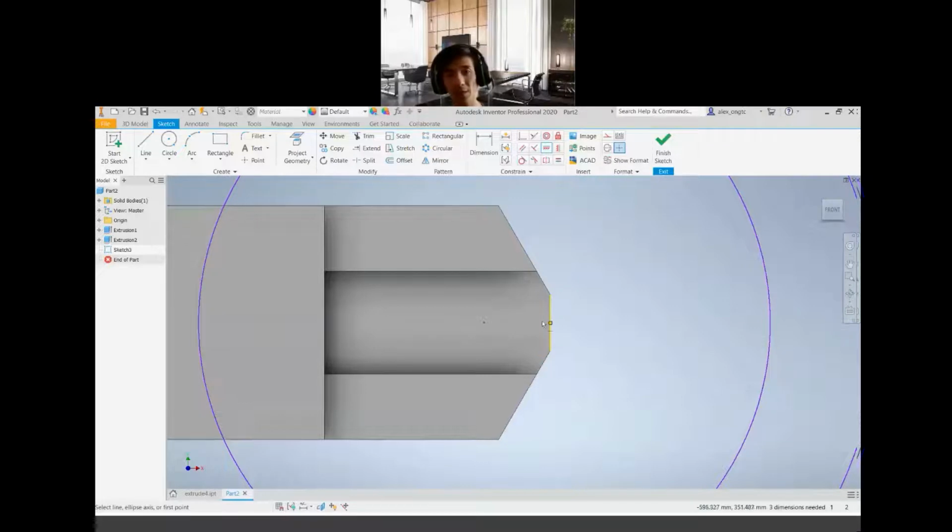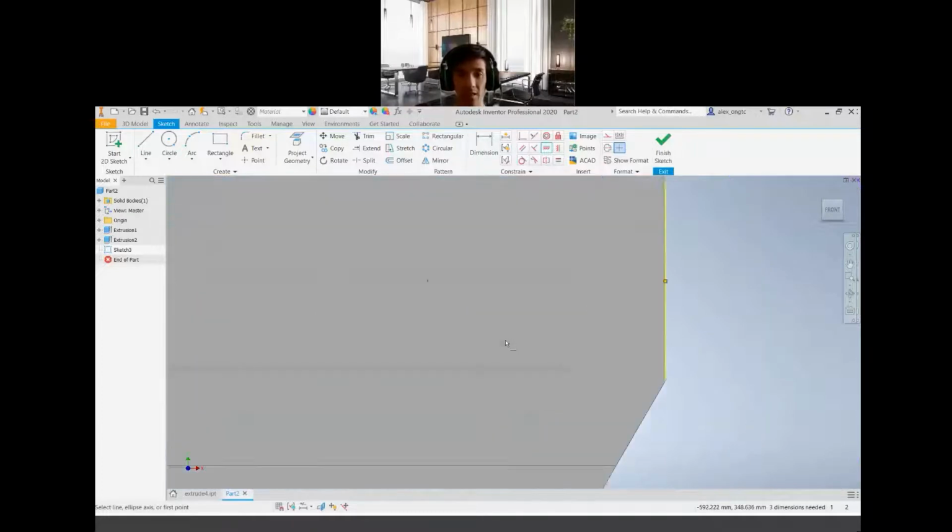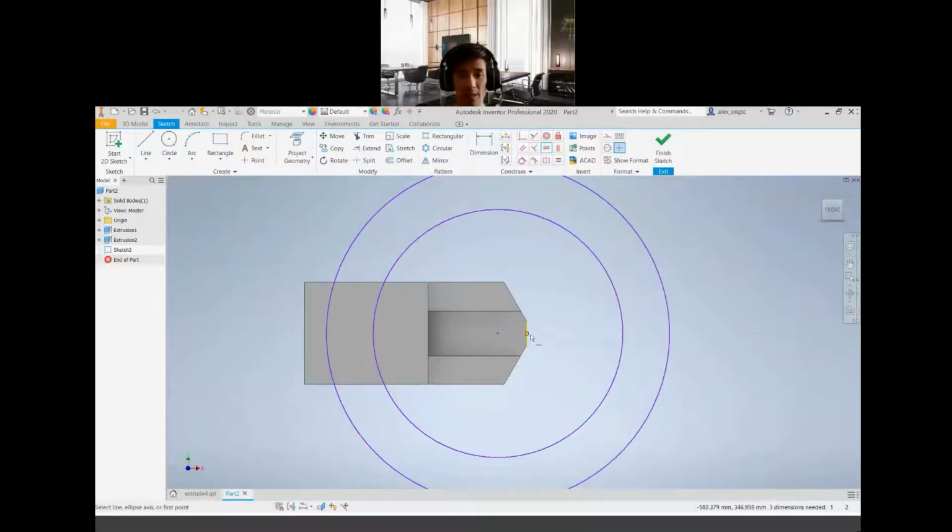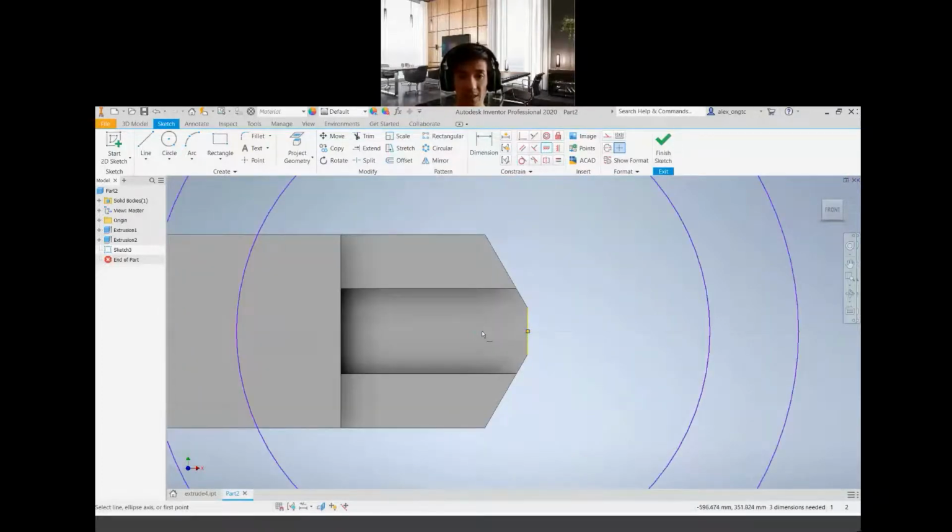Same horizontal axis. If you apply vertical or horizontal, it actually joins up to here. Then you undo. Okay, undo. Undo, then you apply the opposite one, vertical. Okay, so that's the first constraint that you should apply to ensure that the midpoint here and the center point are at the same horizontal axis.